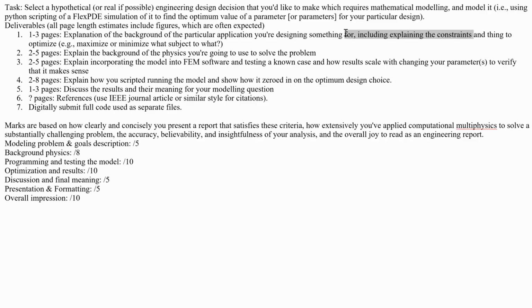And what we need to do is design a thermal strap that's going to get the heat away from this thing into a reservoir that's, let's say, at some fixed temperature of 20 degrees C. And what we need to optimize is the thickness of this thermal strap given a fixed width, or maybe the width given a fixed thickness, if the material is determined. Optimum being minimum weight that would get the certain temperature, that would make sure that the temperature of this computer chip stays below a certain amount after a certain time.